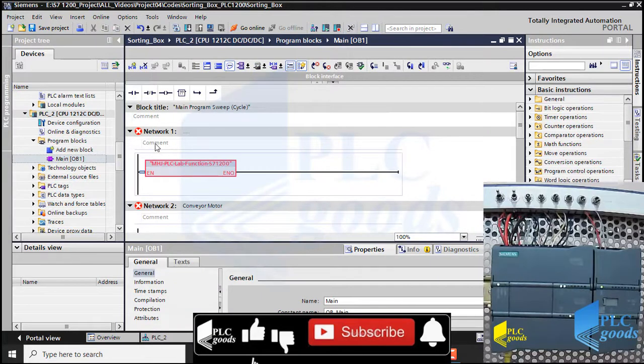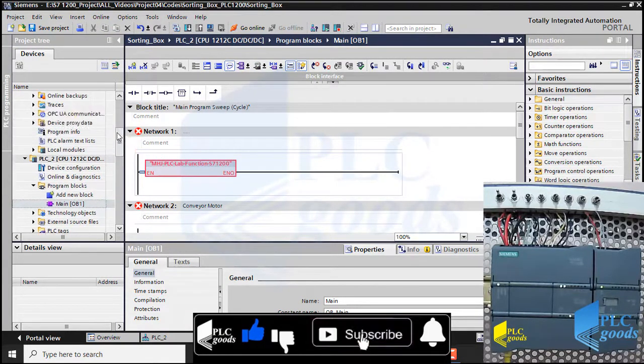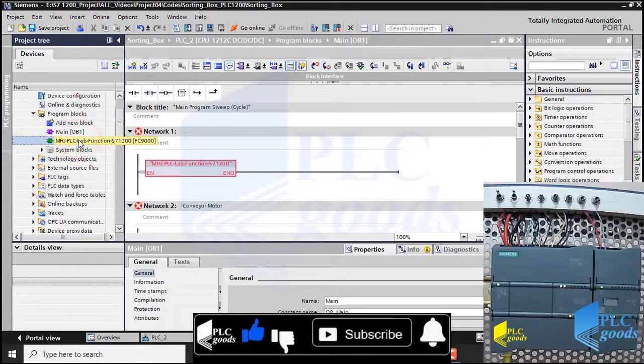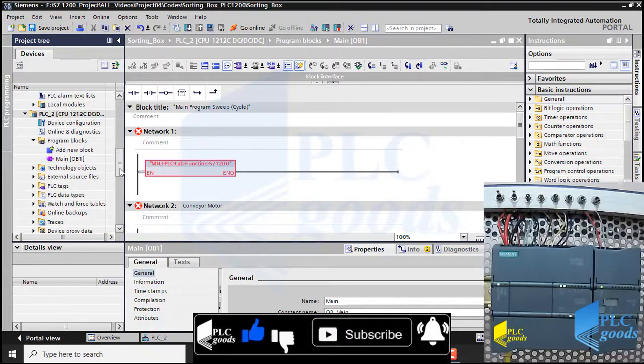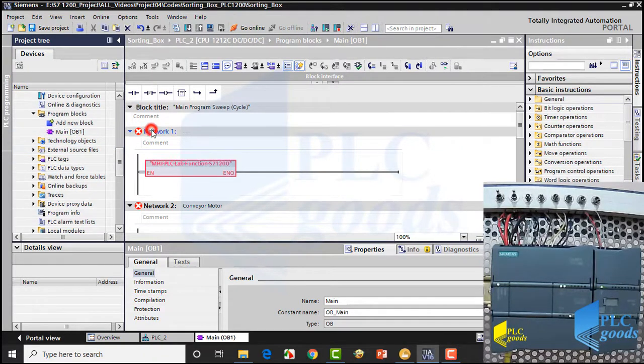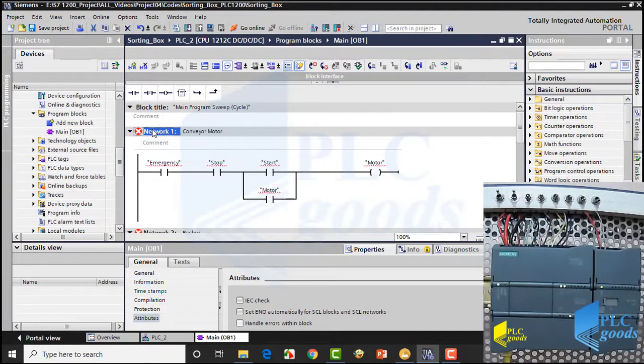If you remember, we needed this function to connect the virtual PLC to Factory I/O, which has been defined here, in the previous PLC. Now, I'm going to use the real PLC, so I don't need it, and can delete it. Also, we have defined some tags in the sorting box program. The new PLC needs to know each tag address.